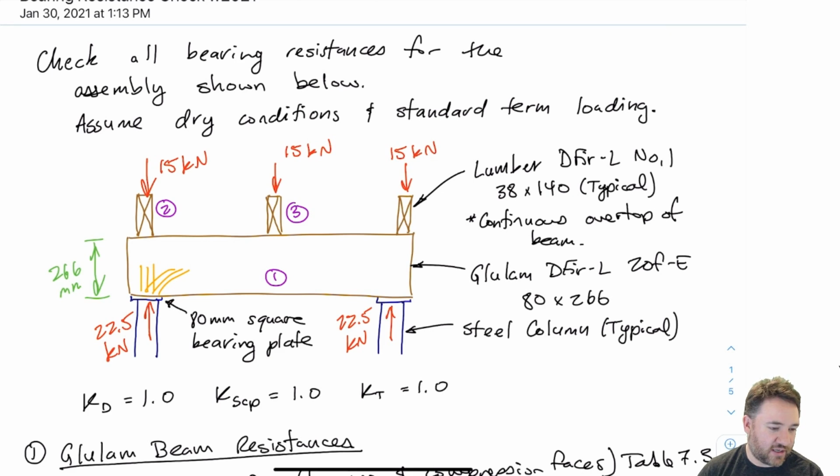The second one is, is the joist in an area of high bending stress for the beam? And that is something that you need to determine based on your own discretion. So you should assess how high the bending stresses of the beam are. Now, this looks like a really chunky beam for not very big joists. So the loads are probably not very high. Maybe I'm only within 10-15% of the total bending resistance of this joist. If that's the case, then maybe I'm not in an area of high bending stress.